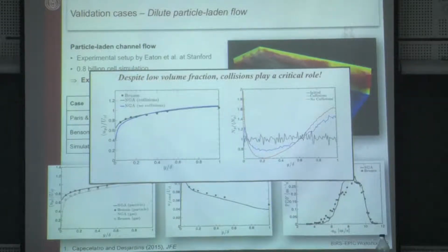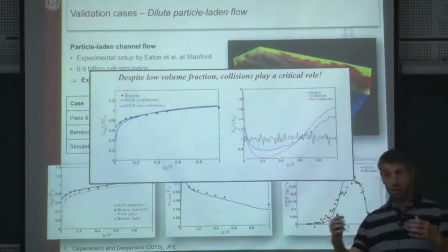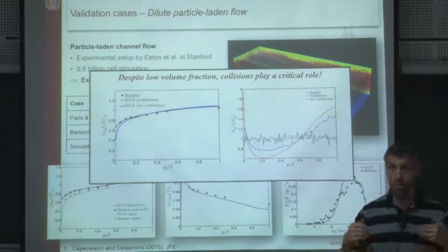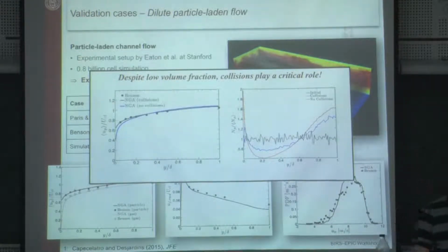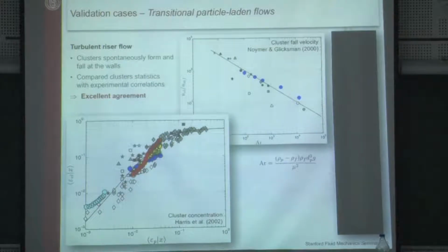Yes, the overall mass loading is low, but there's an explicit two-way coupling process that leads to particles getting pushed systematically against the wall. So locally, concentration becomes high. Collisions do become important. Okay, so this was a successful validation for dilute two-phase flows.